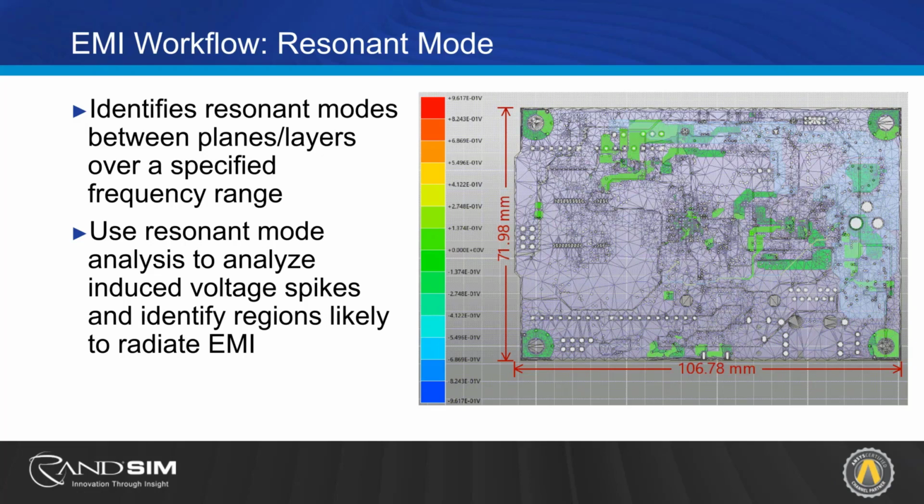And so using these two tools together, this is a very quick pinpoint as to where you have EMI and what parts of the geometry on your layout you might need to consider fixing. So here it looks like the region that we see with the greatest color change.